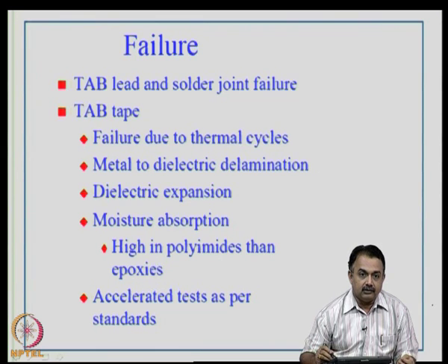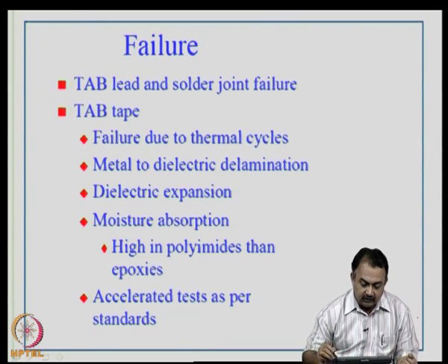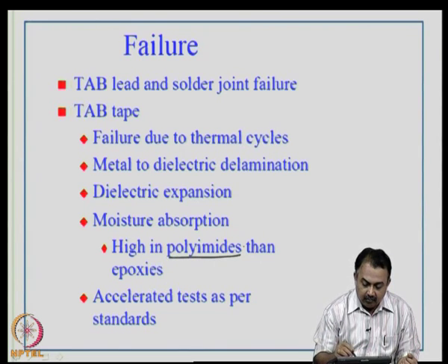The tape material that is used can fail due to thermal cycles. There can be delamination between the metal and the dielectric material at the lead frame area. The dielectric should not expand. There should be less moisture absorption at the dielectric choice that you have taken, whether it is a polyimide or an epoxy or cyanate esters and so on. The moisture absorption property is an inherent property of these polymers. So, it is very high in polyimides and epoxies, but if you look at the